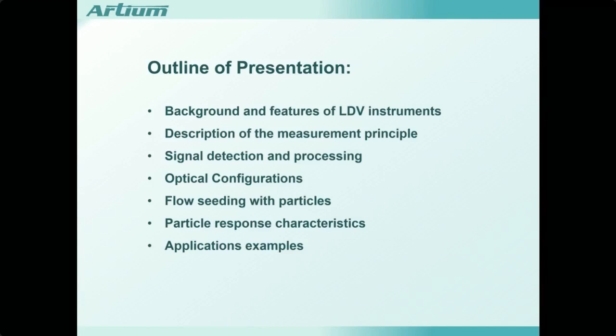I'll talk about seeding with particles and the particle dynamics which are associated with that approach. I'll discuss particle response characteristics because the LDV method actually measures particle velocities rather than the direct gas phase or liquid phase velocity. So particle response is a critical component in getting reliable measurements. And then I'll give a few application examples if time permits.